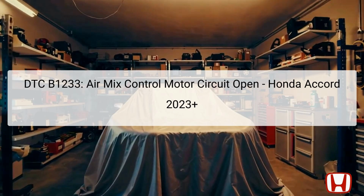The air mix control motor is responsible for blending the air temperature by opening or closing based on user settings and environmental conditions. It is usually located within the HVAC, heating, ventilation, and air conditioning system of the vehicle, especially in the vicinity of the climate control unit. When this DTC is triggered, it can significantly affect the climate control performance, potentially leading to improper temperature regulation inside the vehicle. Understanding the functionality and interrelationship of these components is critical for effective diagnosis and repair.